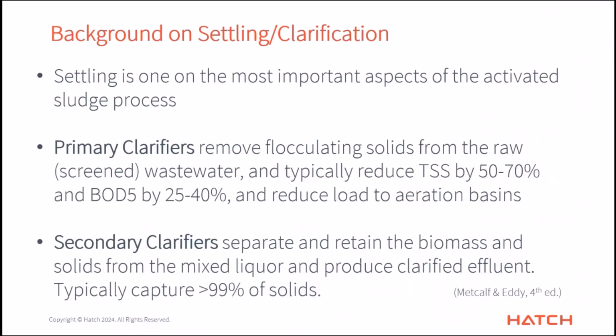Right. Well, settling certainly is one of the most important aspects of the activated sludge process. So primary clarifiers are there. I've heard them many times referred to as sort of the workhorse of the activated sludge system. They're there to get out all of those organic and inorganic solids that are coming in the raw wastewater.